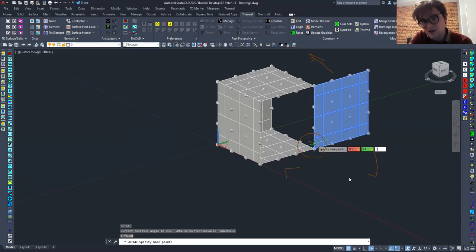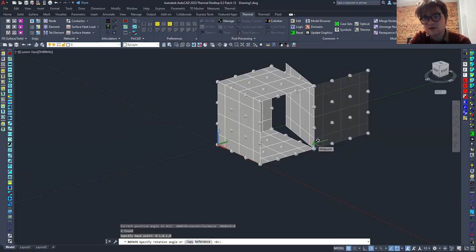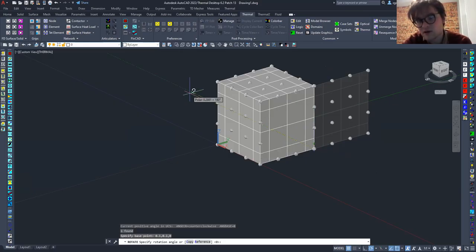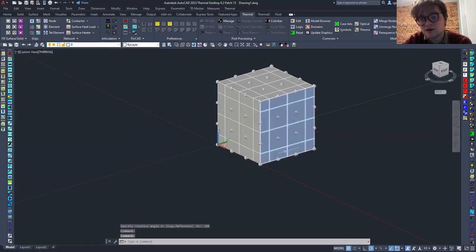So set your point, hit enter for that. And then it should ask you for a degree to rotate by. I think you can type 180. If you hit 180, it should flip it, and then hit enter once you're done with the 180. And there it is.